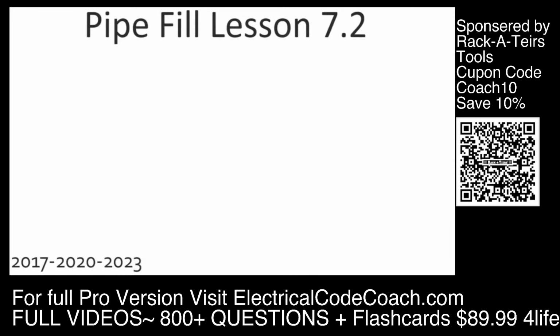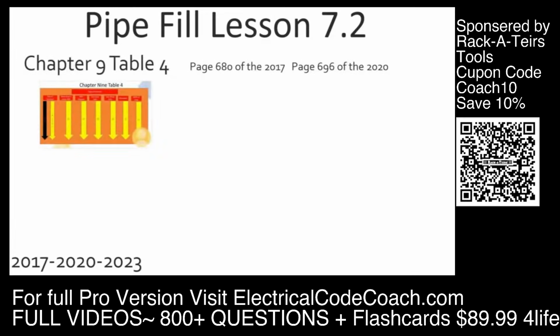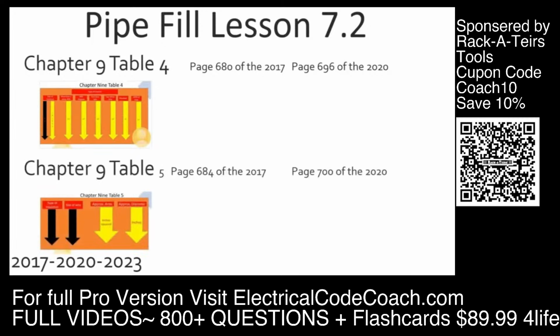I am the Electrical Code Coach, and we're picking right up in pipe fill. This is lesson 7.2. So in our previous video, we learned that if the conductors are all of the same size and insulation type, we can just head straight to Annex C to answer all of our pipe fill questions. But when they're not, we're going to learn about what to do today. We're going to learn about Chapter 9, Table 4 and Chapter 9, Table 5.